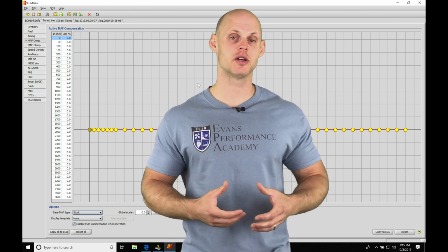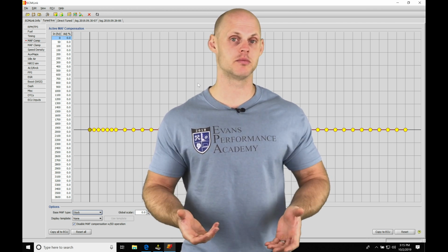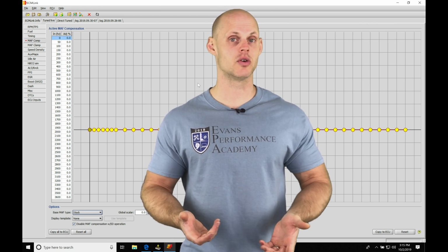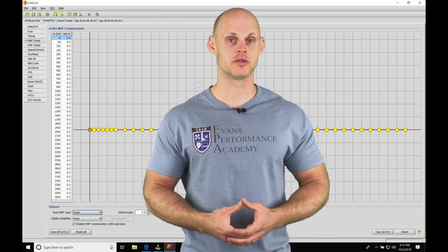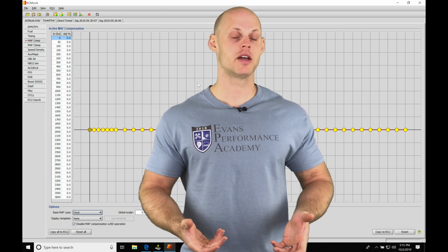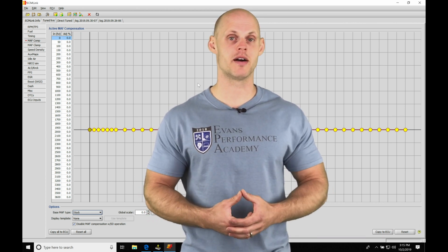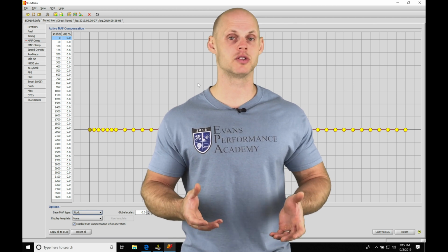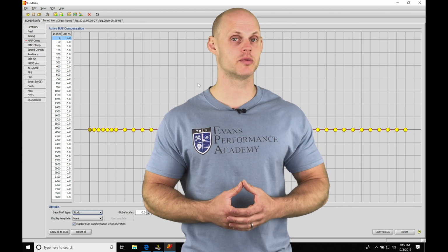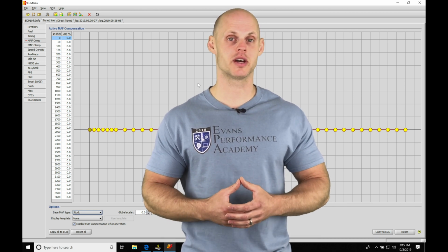So this is going to be a two-dimensional table. It's going to allow us to make adjustments based on different frequency ranges of the mass airflow sensor. Now, if we've installed a different mass airflow sensor, such as a GM, we're able to recharacterize the MAF curve and do some fine tuning with our MAF compensation table. I'm going to go over both situations in this video so it's very clear how to do your adjustments and what you need to look for. So without further wait, let's jump in so we can check this out.